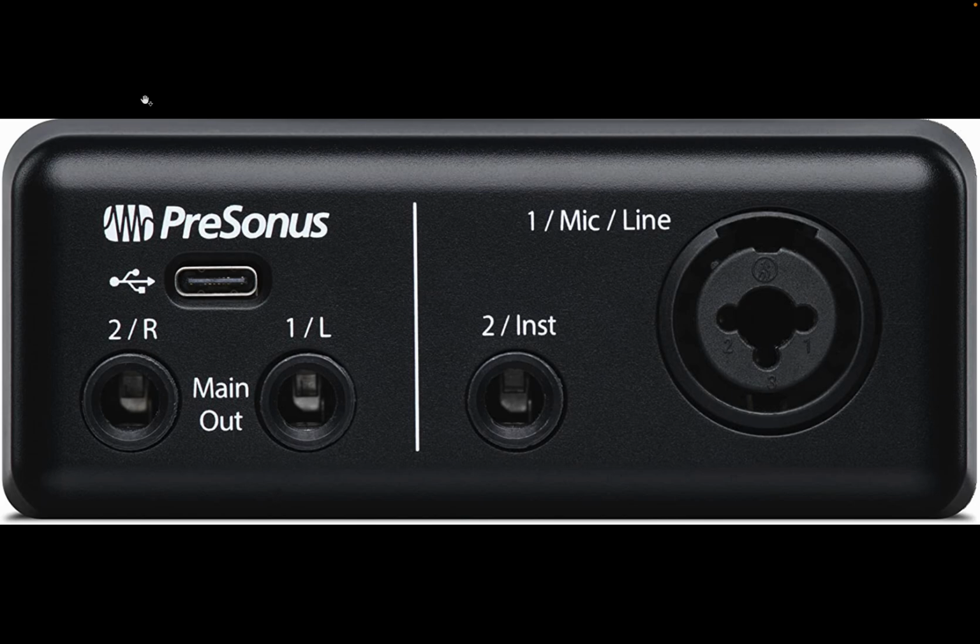So in this particular case, you could use this to provide a connection between XLR or whatever your other microphone happened to be to your computer because if it's going to go into your computer, you need some way for that analog style signal to be converted into something USB that the computer can understand. And so it needs some kind of vehicle to actually make that happen. And in this case, it's a USB-C connection. Now, again, if it doesn't specifically say it has phantom power, you're going to need to find something that can provide that phantom power.